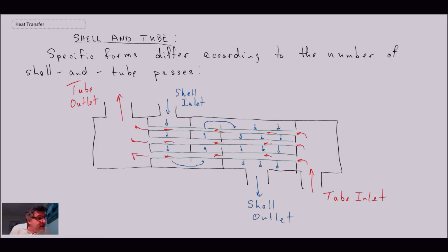So that is the direction of the two fluid streams, and we have a couple of other things in the construction here that I would like to point out. First of all, there are these plates here. You can see two of them in my drawing. These are called baffles or baffle plates, and there are different designs that they have. Sometimes they'll have designs where it's like a helical pattern, and you get more efficient mixing that way. Because if you look at the fluid mechanics here, this is horrible fluid mechanically. You're going to have massive separation downstream of these baffles when the flow comes around, and you'll have significant pressure drop. Usually we're not worried about that much pressure drop with these units.